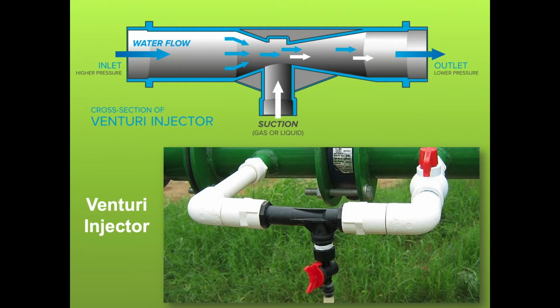With the rest of this piping, this is the kind of thing you could do for probably less than $100. And a 3/4 inch Mazzei will do multiple acres, depending on what you're trying to inject and how quickly you're trying to do it. I use these a lot with chemigation. I work with an entomologist at Auburn, and we do a lot of chemigation. There's a lot of products that can be injected through, and actually some fungicides that have some systemic activity. If you ever decide to get into something like that, you'll see a lot of pesticide labels do allow chemigation. This is a good one to start with because it is precise.